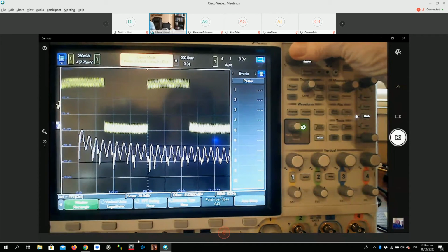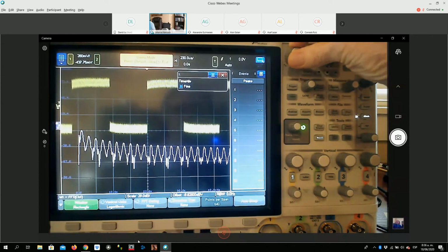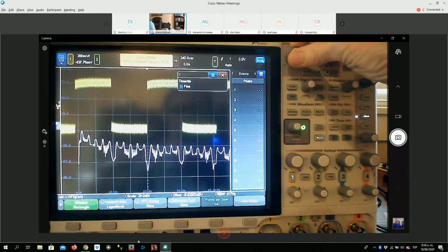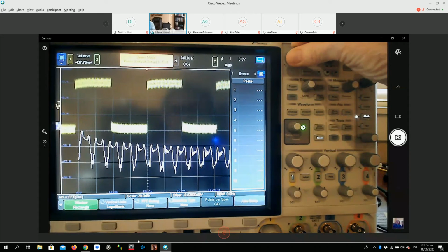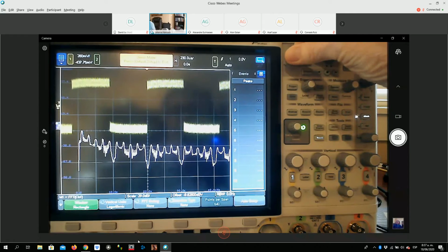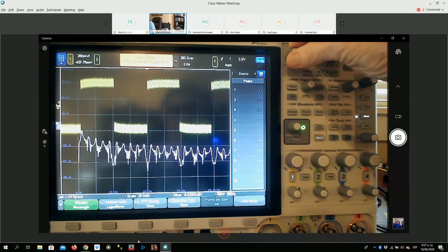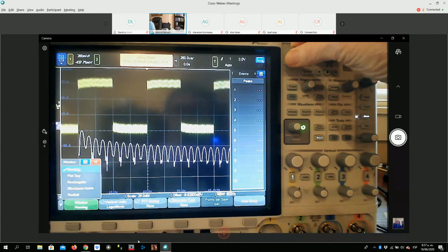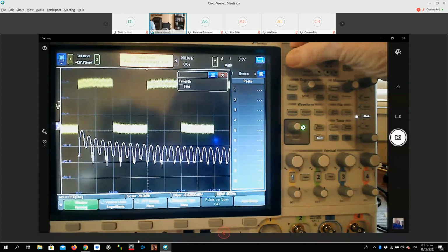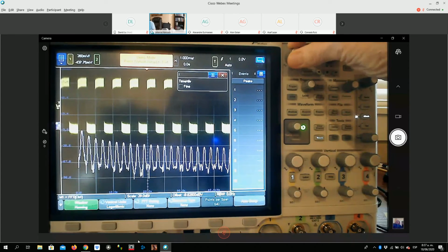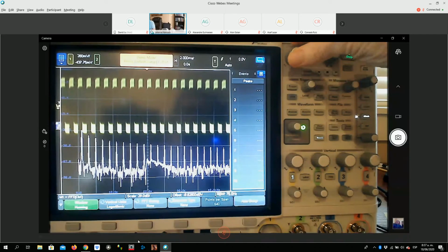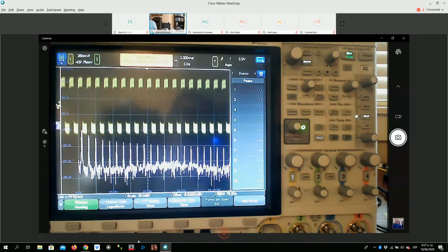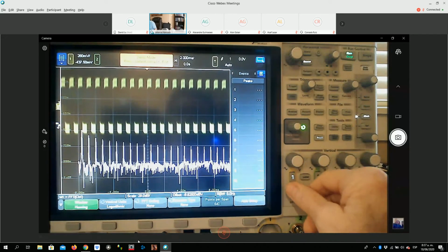But watch what happens. Now I've scaled on some partial cycles, and the FFT waveform is just kind of falling apart with the rectangular, whereas if I go back to Hanning, it looks good again. Now, my recommendation, if possible, is to scale more cycles on screen like you see here.